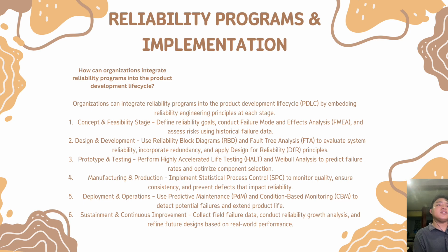Next is the design and development. Use RBD and FTA to evaluate system reliability. Incorporate redundancy and apply design for reliability principles. Next is the prototype testing. Perform highly accelerated life testing and Weibull analysis to predict failure rates and optimize component selection.